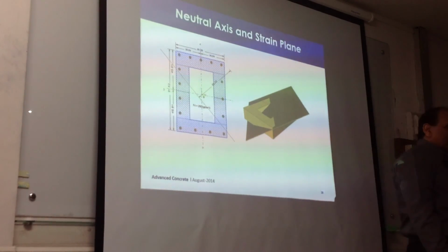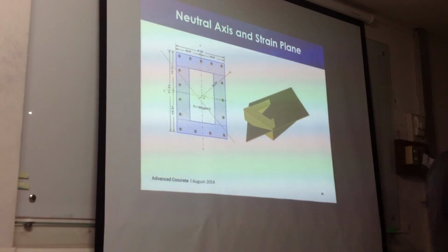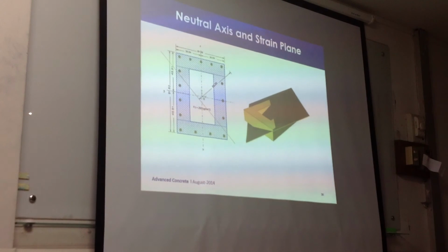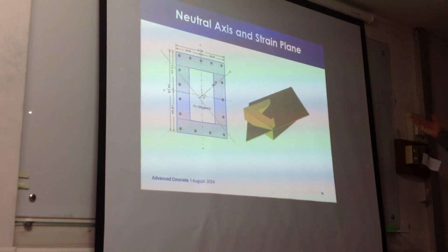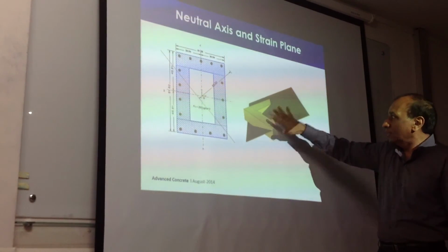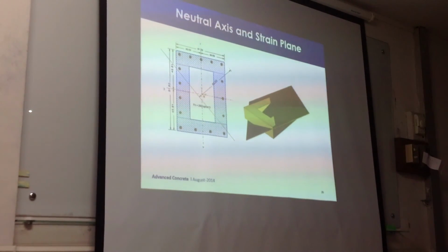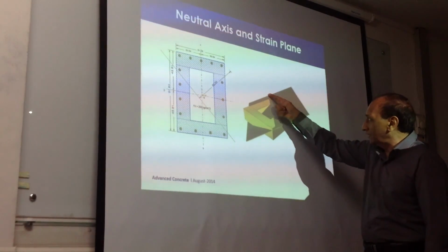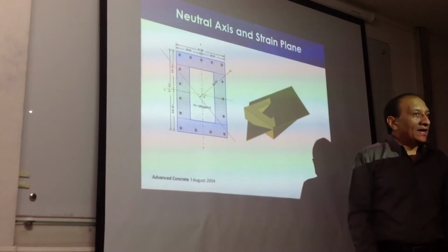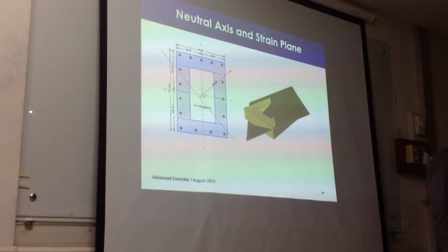Right? Now, just to tell you, the deformed one is not a plane. We are just assuming it to be a plane section. We have warping, or you can forget about that. Which means this cross section, this dark gray line, is not actually a plane. It could be a surface all deformed and curved, which we do not know. That means the intersection of that may be a curve, not a straight line here. It could be intersecting. It is even possible that this thing is going up and down, so you have two intersections on the cross section. So you have two neutral axes or more.